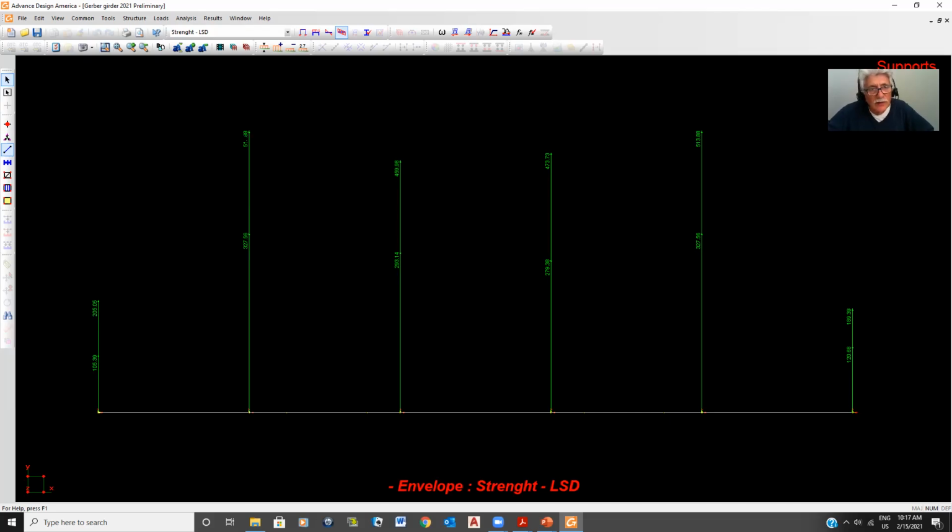So in other words, this is the PF that's going down into the column. This is the PF that's going down to, so we're going to take the CF value, or this is CF, we're talking about steel, sorry. In steel, they call it CF. This is our CF value, and therefore we already know what's the resistance the column has to have based on this PF value. So that's the first thing I look at, and this looks pretty much good.